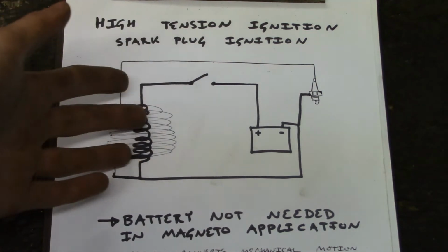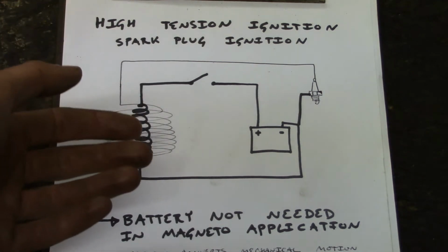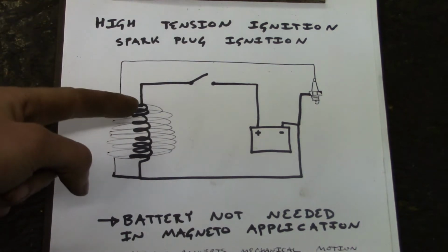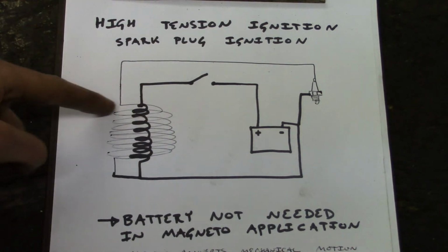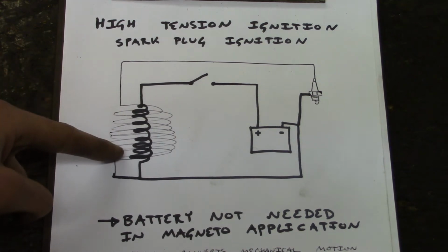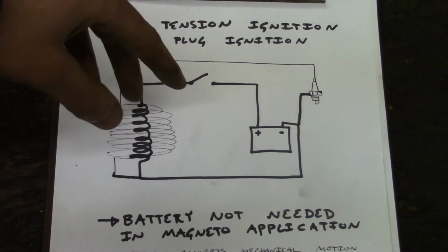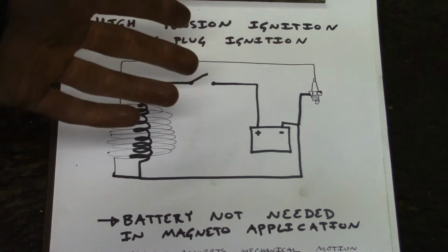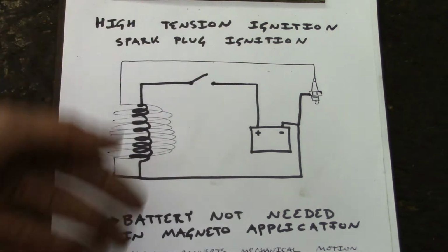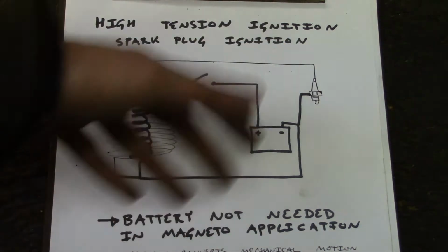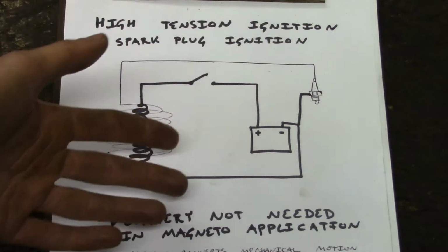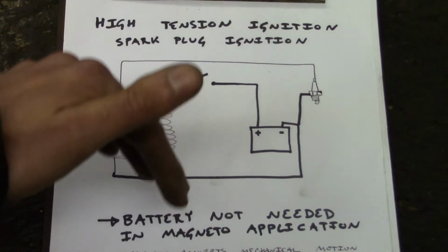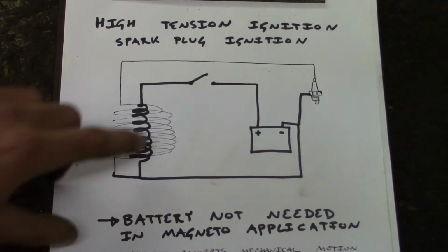Now another thing about this whole inductance concept is that you can use this to step up or step down voltage depending on the number of turns in your primary coil and the number of turns in your secondary coil. That's also what's going on in the transformers that are on your power lines, your telephone poles that deliver power to your house. The line voltage on a power line along the road, I don't know what voltage it is, but it's a lot higher than what you get into your house, and those transformers step down the voltage with this same concept.